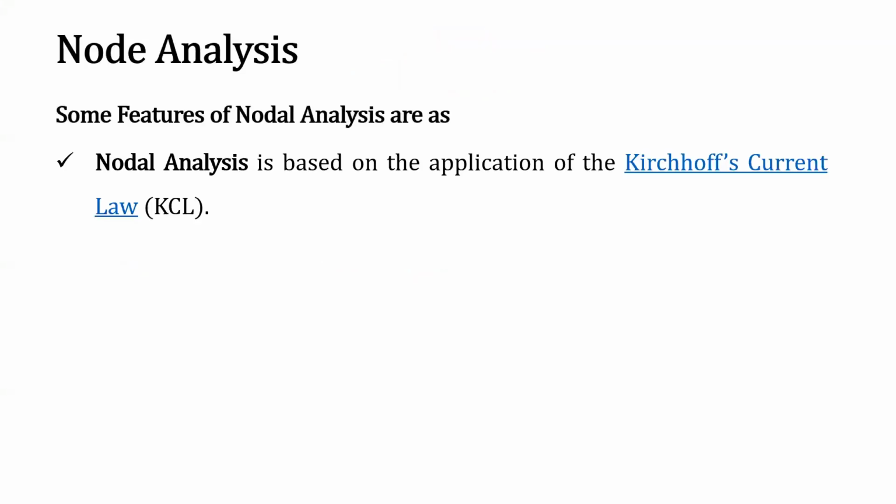Features of node analysis. Node analysis is based on Kirchhoff's current law, KCL. We know KCL: at any node, the summation of incoming currents equals the summation of outgoing currents, or else the algebraic sum of currents at any node is 0. Node analysis is based on KCL, right?